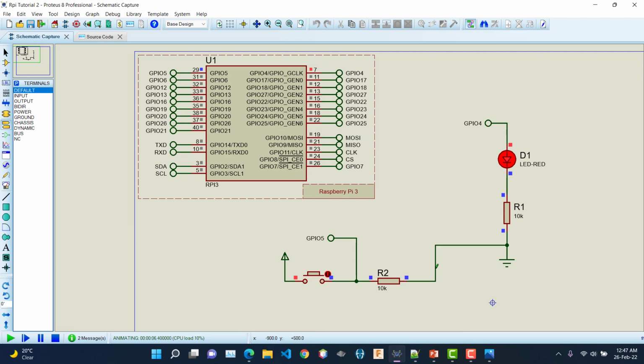Okay, if you look here closely, you can see that the ground is denoted by a blue dot, and you can see a blue dot here. It means it is by default connected to the ground, or it reads it as 0 volt. So when you push the button, you can see the state has been changed to red. If I click it again, it is red. So it means when I push the button, this pin gets connected to the positive terminal, so it would read it as high.